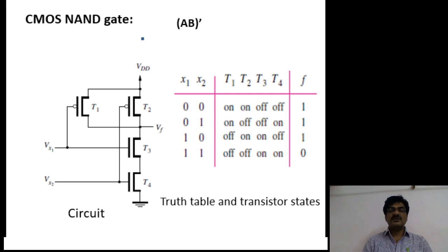And with reference to last combination, that is 1, 1, both PMOS transistors are in off state, whereas NMOS transistors are in on state. Hence the pull down network is the short circuited mode of operation. Hence the output is very low voltage, hence considered as logic 0 output. So like that you can develop the functional table for any CMOS structure.